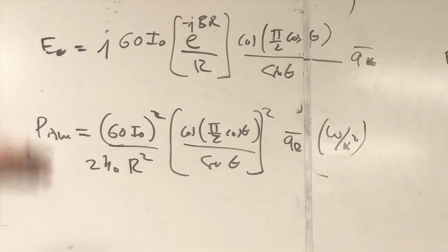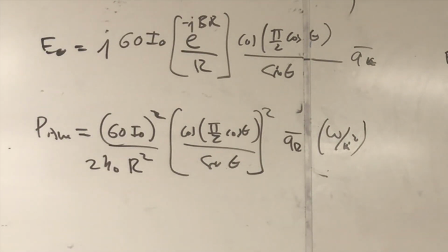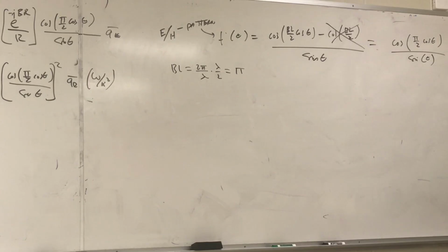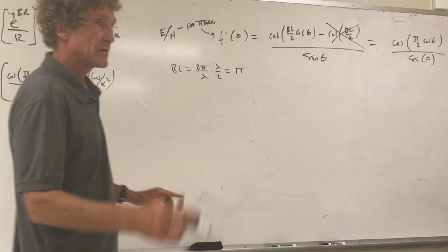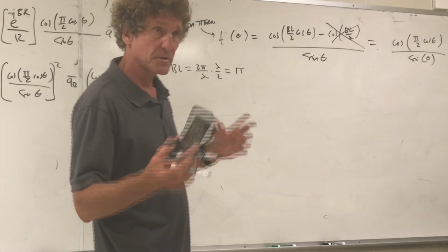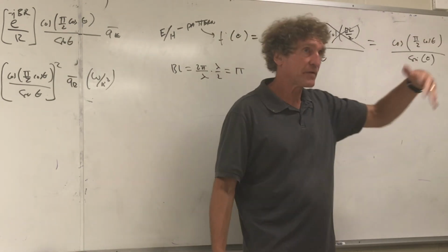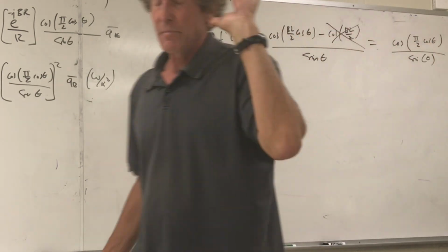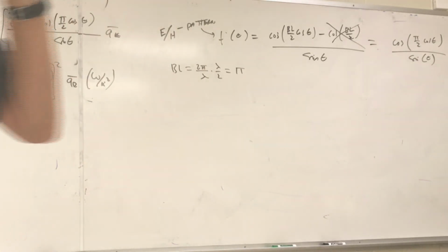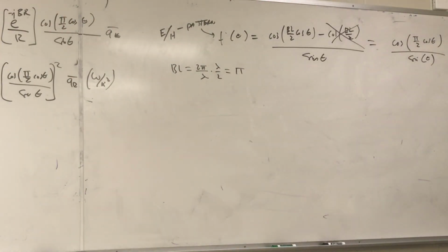I'm just showing you that what I've done is nothing more or less than squaring the E field divided by 2 eta naught. I want to show you what it goes to though. And I'll tell you what I'll give you. For a quiz or something, I'll give you the actual value of f, small f of theta, the angular variation. Maybe I'll give you the electric field and the power density for a half-wave dipole. I mean the form of it. You all with me, class?